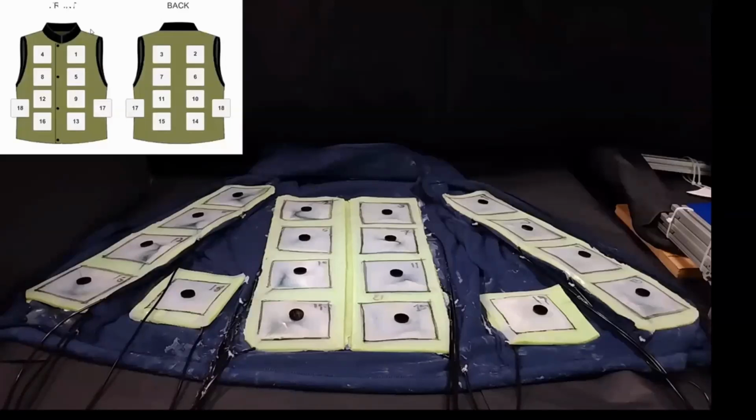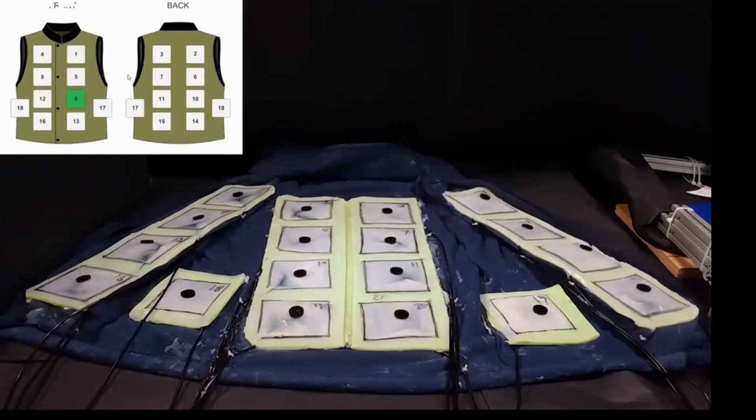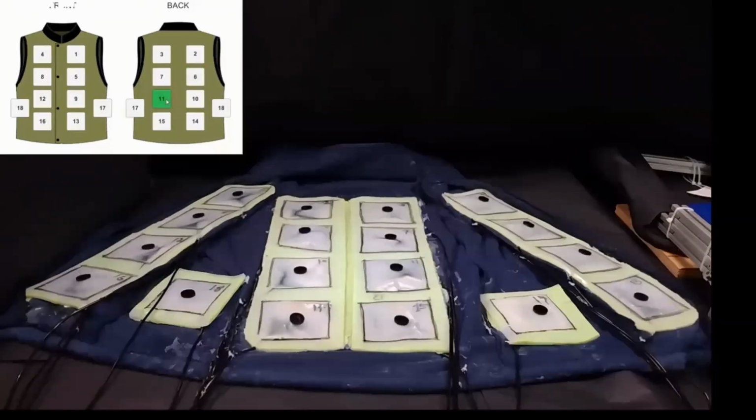In addition, we also demonstrate the implementation of a fluidic matrix circuit for controlling a haptic vest, consisting of inflatable airbags that provide force feedback to the user when the bag is inflated. The pouch attached to the haptic vest was rapidly deflated to give a sensation of being hit by an object, and the deflation of the pouch was accelerated by generating vacuum using fluidic modules connected to the corresponding pouch.